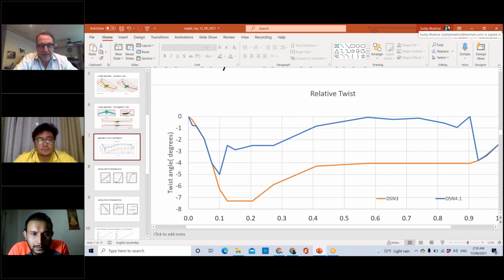And if the airplane's still stable enough, you might have to slide the CG aft just a little bit to get it to trim, and that's okay. Just to do this experiment, that'd be fine. So did you say slide CG aft, further aft from the position? Right. If your elevons are overworked, trying to trim out the change in washout.